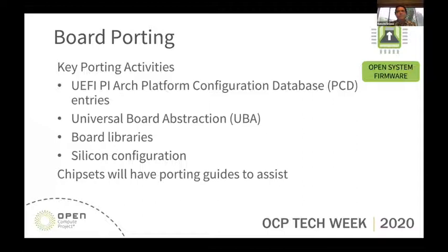So there are several libraries defined in the MinPlatform specification that you need to implement in order to build a MinPlatform board port. The most important of these is BoardInitLib. It's very similar to mainboard.c in coreboot, actually. There are a few others as well. Like there's one for very early code, SecBoardInitLib.